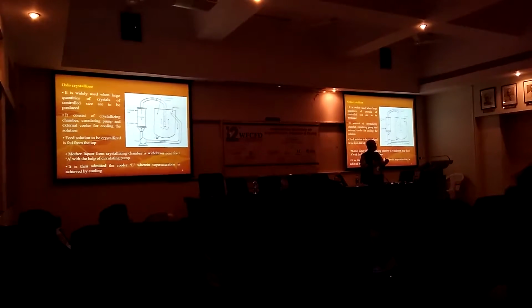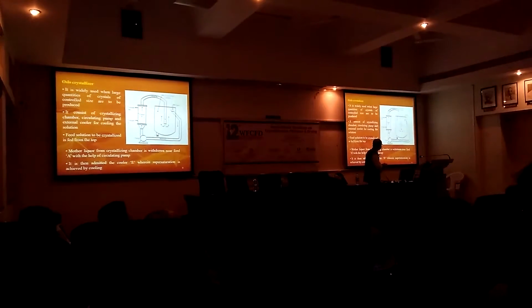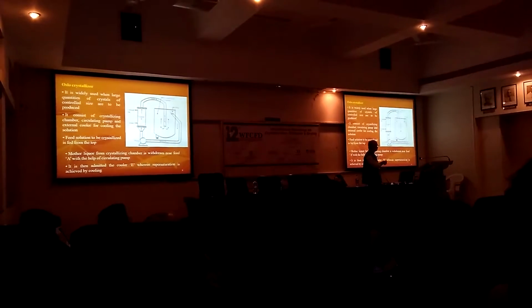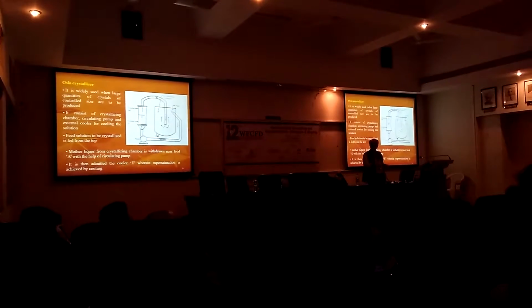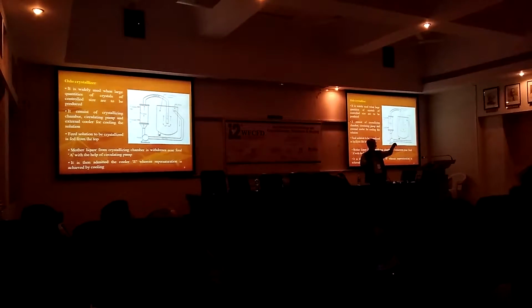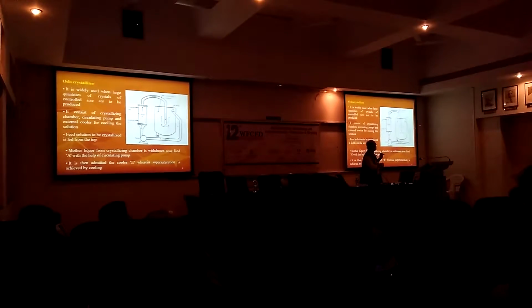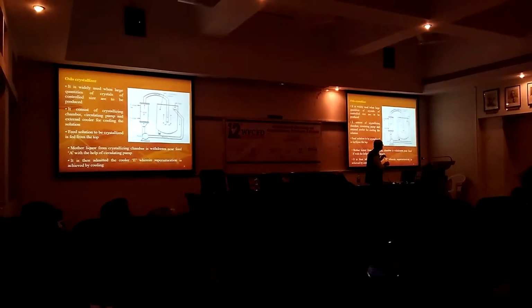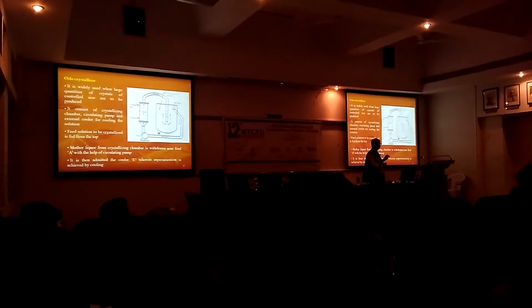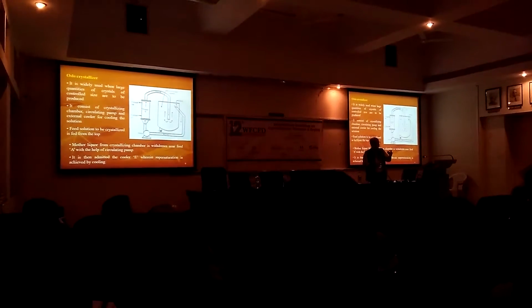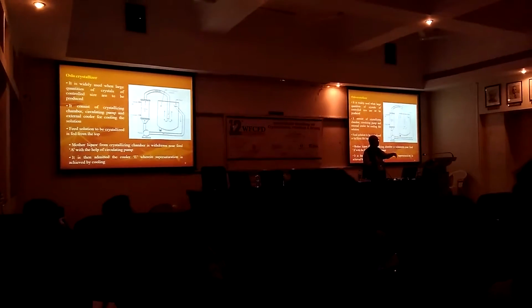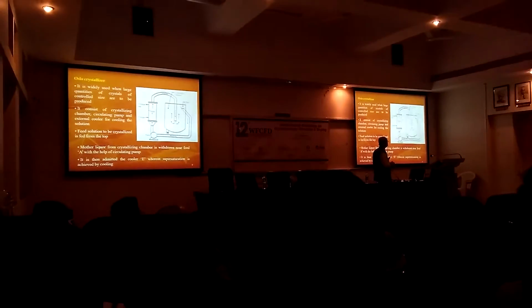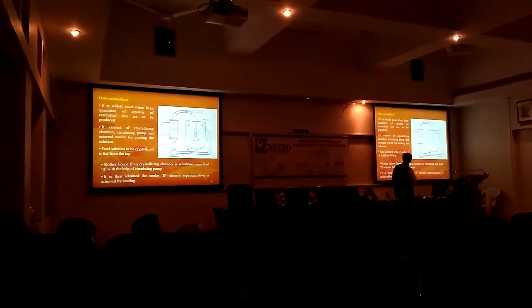In the process, they will grow and then keep on taking up lower and lower positions after each circulation through a cooling zone, and essentially you will get layers of crystal sizes, starting from the smallest crystal size in the upper layer and the largest crystal size in the lowermost layer. Depending upon what crystal sizes you want, you can collect the material and get the crystal size distribution as you want.